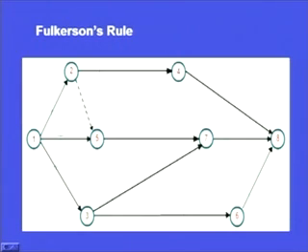Suppose we have numbered node number 1 initially, then we will call it node number 2. If there is a conflict, there are two such nodes at which there are arrows only going out, there is no arrow entering in, then we will name the top node as the lower number and the bottom node as the higher number. So that was seen when we saw node number 2 and node number 3, and subsequently we will move on, and there may be certain times certain conflicts may be there, but this would help us to identify which node number should be assigned to which particular node. This is just a rule in order to name the nodes or in order to number the nodes.